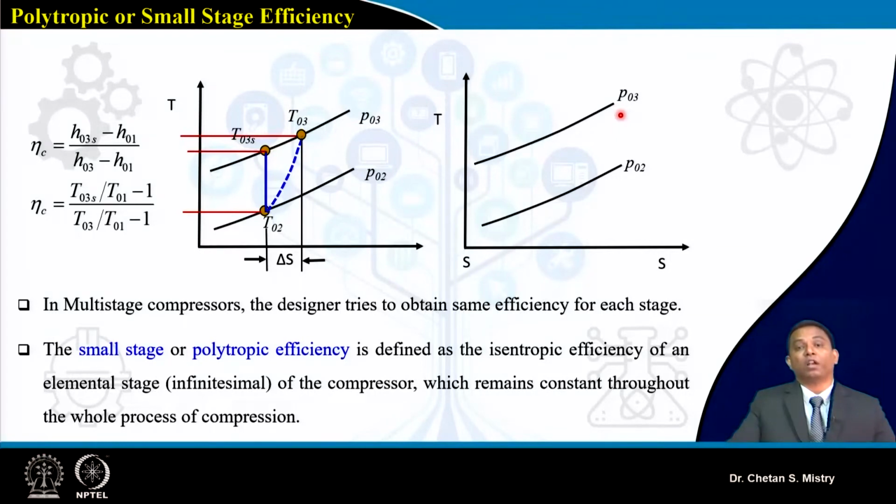As we have discussed earlier, my axial flow compressor is a very sensitive device and it has aerodynamic limitations, and that's the reason why we are going with a number of stages. So that's what we are doing. Suppose I am making my compression process using different numbers of stages. Let me put this process that we have learned on our TS diagram. So for my first stage, this represents my isentropic compression, and this represents my actual compression.